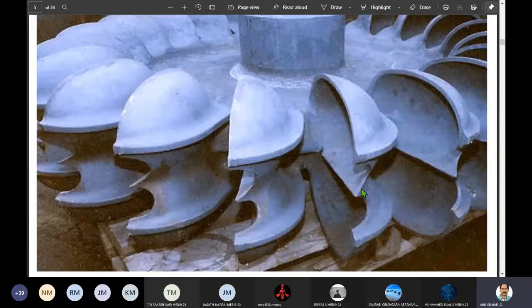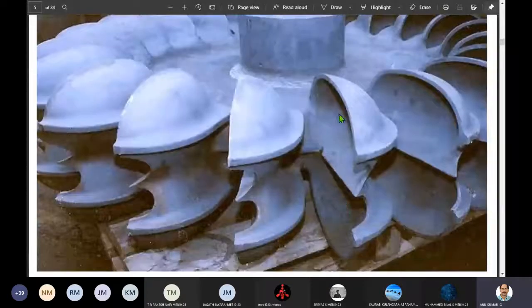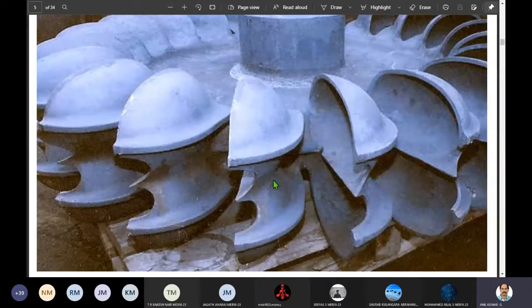See, this is a Pelton turbine bucket. This is called double split, hemispherical vanes, or we call them hemispherical buckets. Don't get confused by the word bucket. Hemispherical vanes or buckets. See, it is double hemispherical, double cups. There is a splitter inside. You can see that these are the blades fitted on the periphery of the Pelton wheel. This is the Pelton wheel runner, or you can simply say Pelton wheel. So it is a heavy wheel along the circumference of which these types of blades are mounted. These are double hemispherical cups, double hemispherical vanes, called hemispherical buckets.